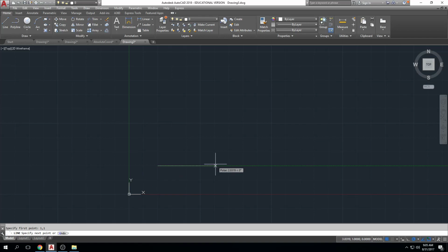The reason that it looks like that is because this grid that is organizing AutoCAD graphically in here, by default is set to half-inch increments. Like Jeff, when he created that exercise we just did in class, he set his background grid to be 1 inch by 1 inch, 1 to 1, so that it would look like over 1, up 1, okay? So don't let this grid back here kind of confuse you.